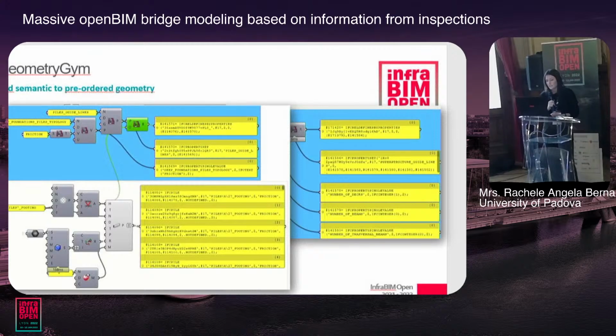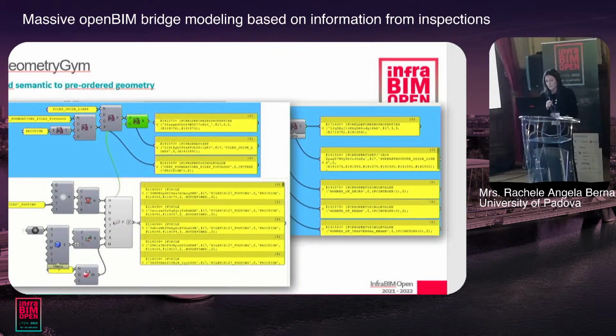Then, what we have done is use Geometry Gym to map the information of the objects into the IFC 4.3 schema, and then also to map the properties and attach the information that was used to create the model as properties of the IFC file.